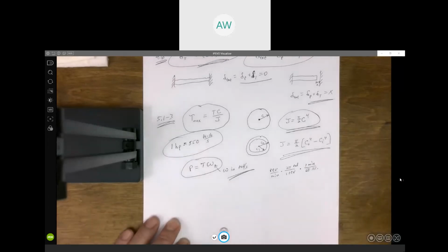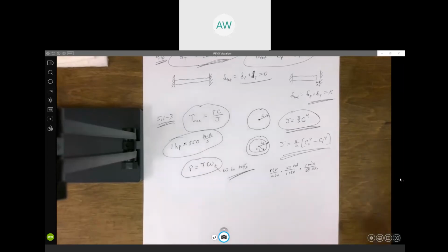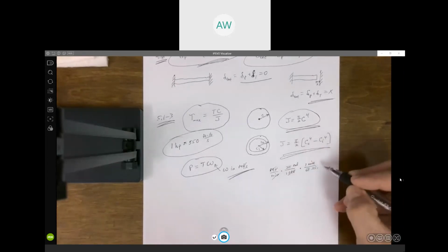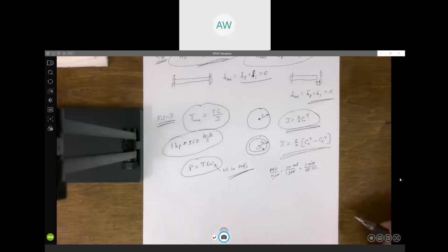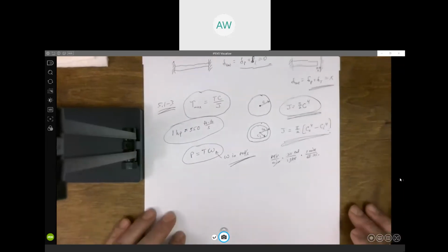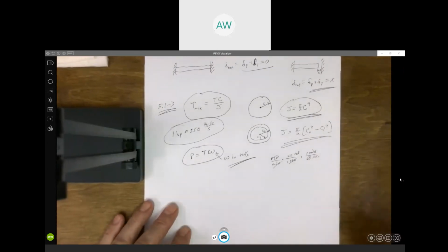And so if you're given RPMs, you multiply by 2 pi, divide by 60, that'll get you radians per second, right? The revolutions cancel, minutes cancel, and we're at radians per second. But that's something you should know. It's not a really new formula. I would hope everybody knows that 1 revolution is 2 pi radians, and there's 60 seconds in a minute.